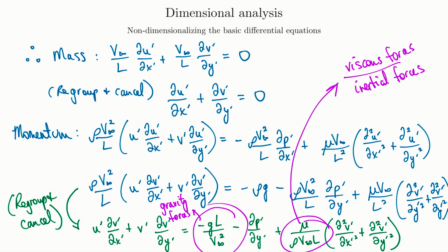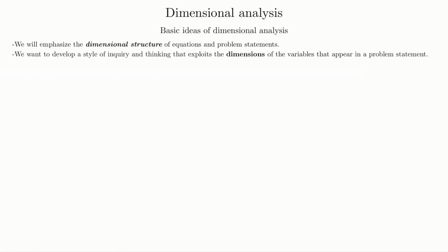Same thing with the Reynolds number. The Reynolds number multiplies out this grouping of terms here with these second order differentials. That grouping makes it extremely hard to solve this problem. So again, if that ratio is very small, I can just eliminate those completely from the equation, and it's way easier to solve in that case, right? Okay, now that's great if we have the governing equations. If we already have the differential equations, this is awesome. We can non-dimensionalize them, find our groupings.